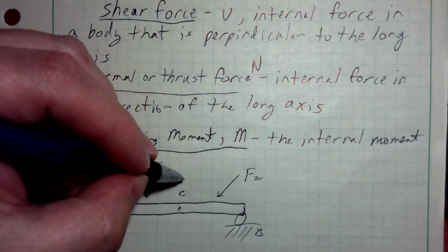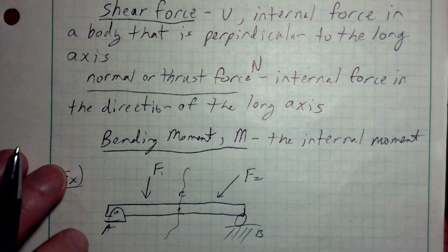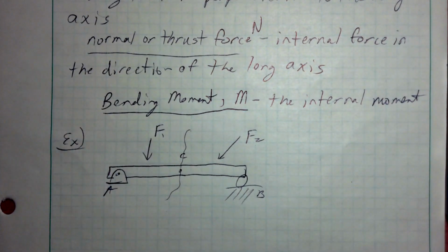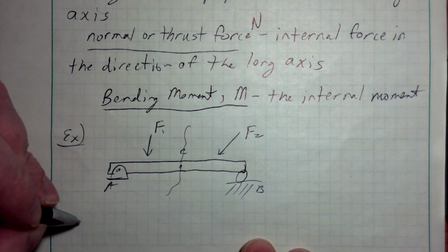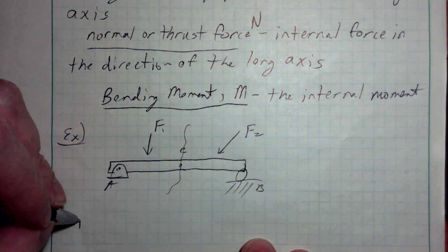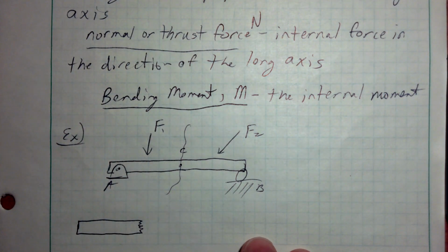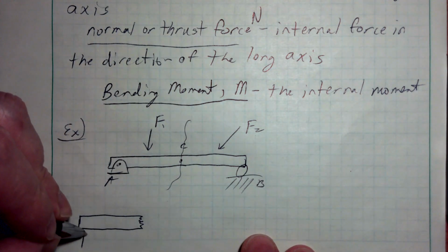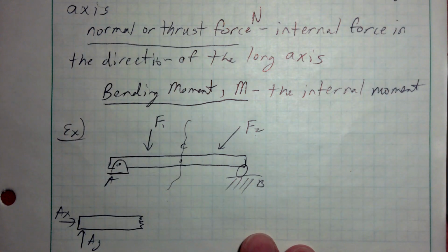And if I were to cut through this beam, this member here, right through point C, again, in quotes, cut. It's an arbitrary artificial cut. If I then look at the two sides of this beam, now I've drawn a cut right there, roughly at point C. When I draw free body diagrams to the left-hand side of the cut, I would have AY and AX, my pin forces there.